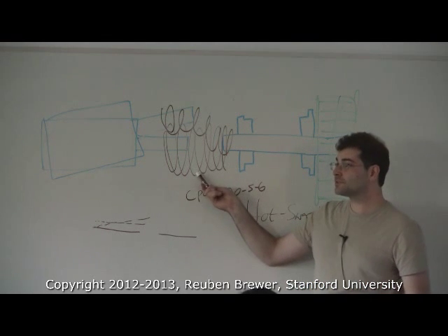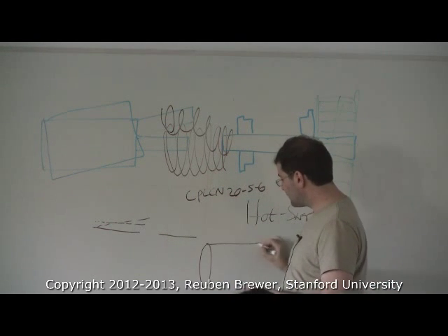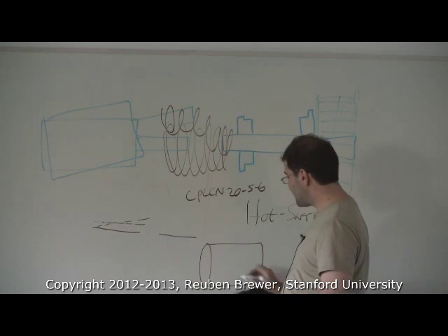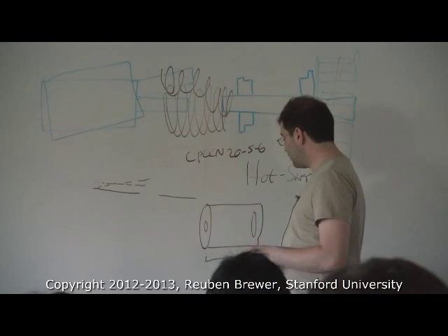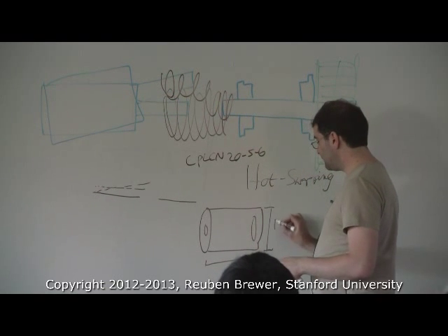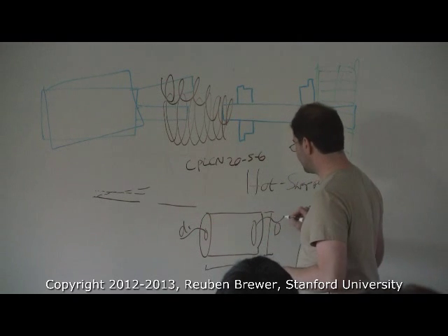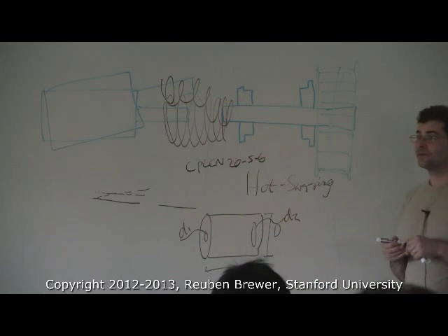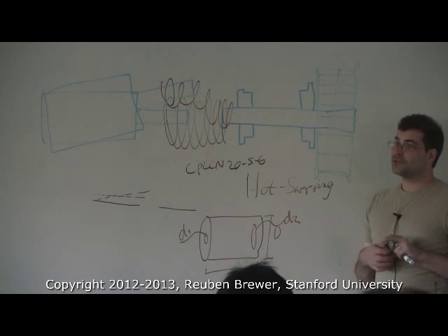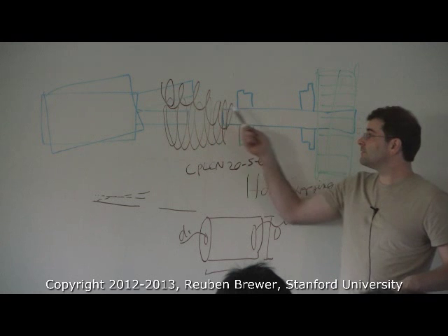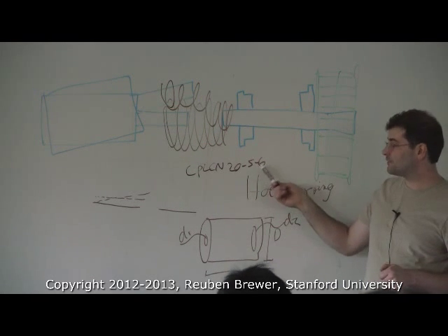20 is the diameter of this, in terms of the big diameter. So let's draw it for a sec. Typically when you're speccing these things, you have a length L, an overall big diameter D, and then we'll call this a little d1. This is a little d2. What are d1 and d2? They are the diameter of the shafts that are coming in and out. So in my case, I have a 5mm motor shaft and then a 6mm shaft after the bearings. So that's what the dash 5-6 is.